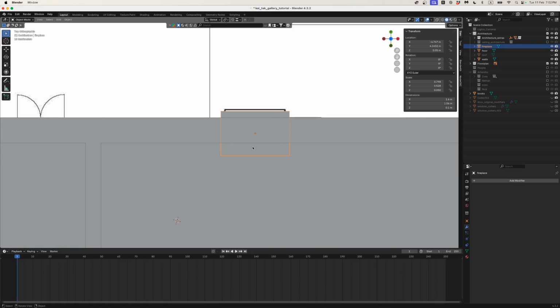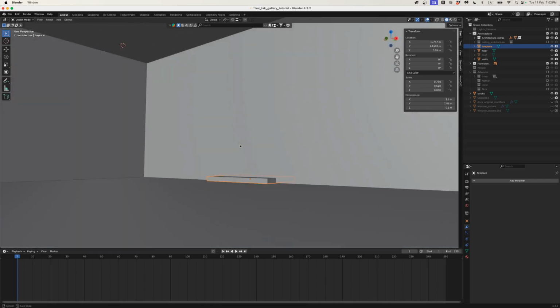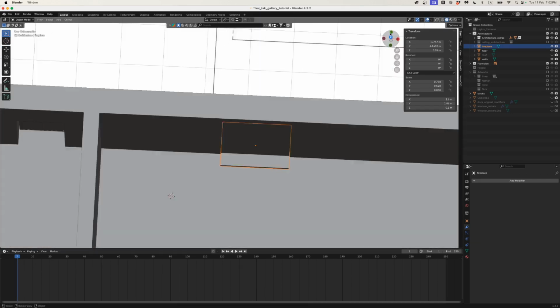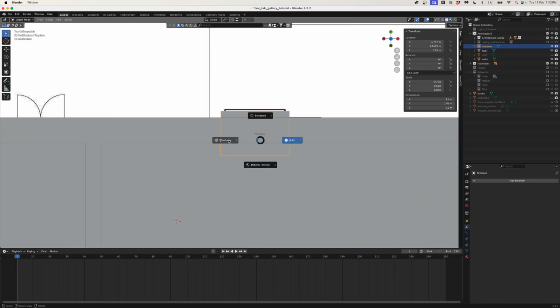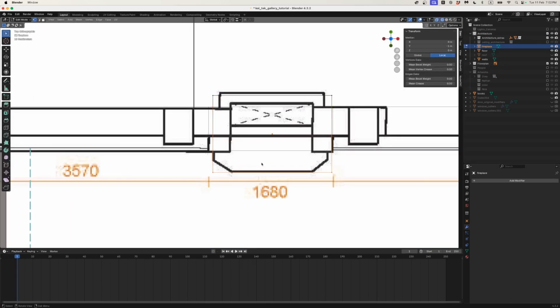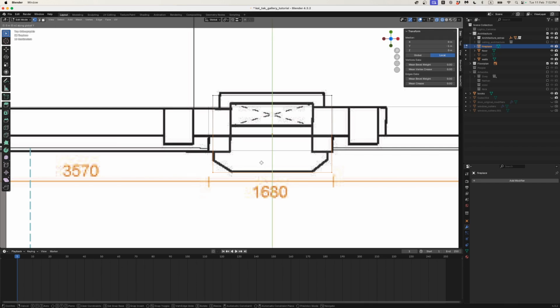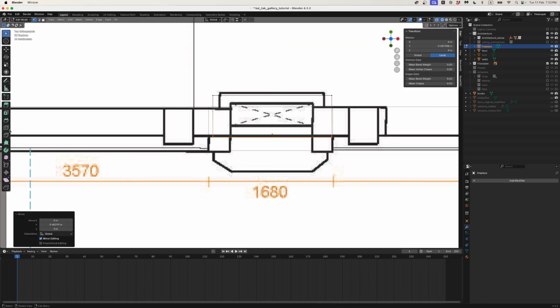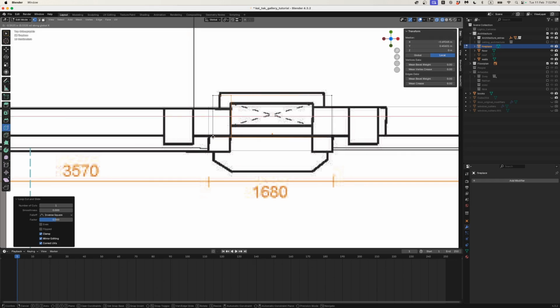Okay, so I've just added a cube here. If you don't have one there, you can just add a cube and get it the right size. And then go into wireframe mode, edit mode, and what's the best way to do this? I'm going to press GY, going to come back here, then I'm going to do a loop cut here, GX, bring it over here, another one here, GX, bring it over here,